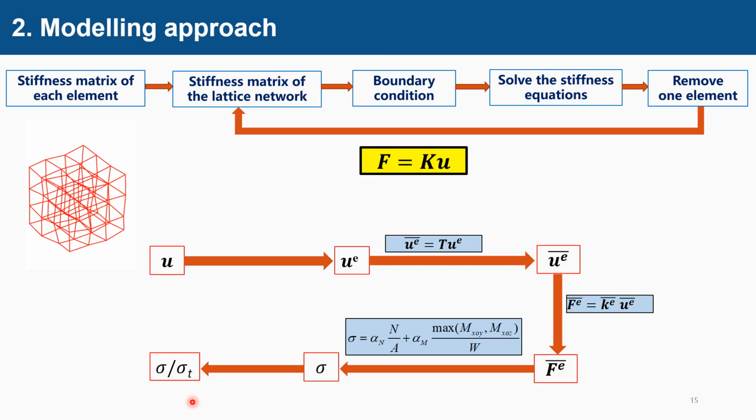from the network. Then you modify the matrix and then apply load again and repeat the computation until the whole network fails. At each load step, you register the load and the elongation of the cube.